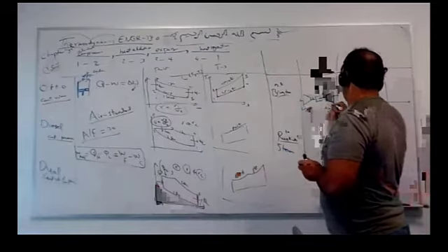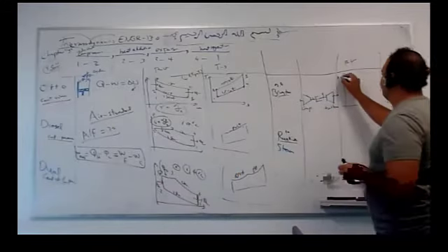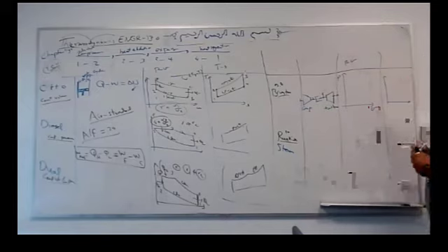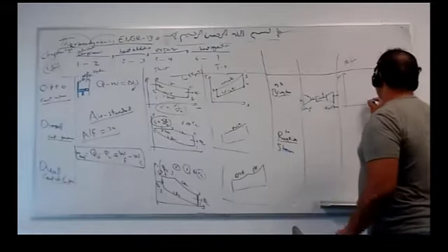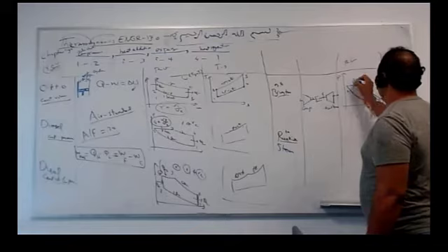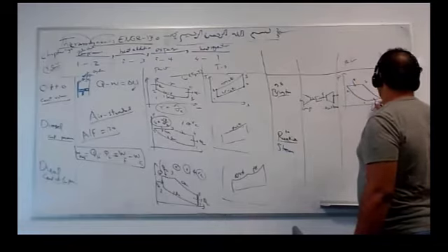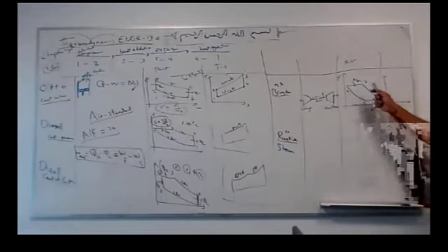Turbine. The compression and expansion are always isentropic. So this is a PV diagram, exactly the same as the Otto cycle, but instead of having heat addition and heat rejection at constant volume, we have them at constant pressure. So we have something like this: 1, 2, 3, 4. Heat addition at constant pressure, heat rejection at constant pressure. So the only difference in terms of the chart is heat addition and heat rejection at constant pressure.